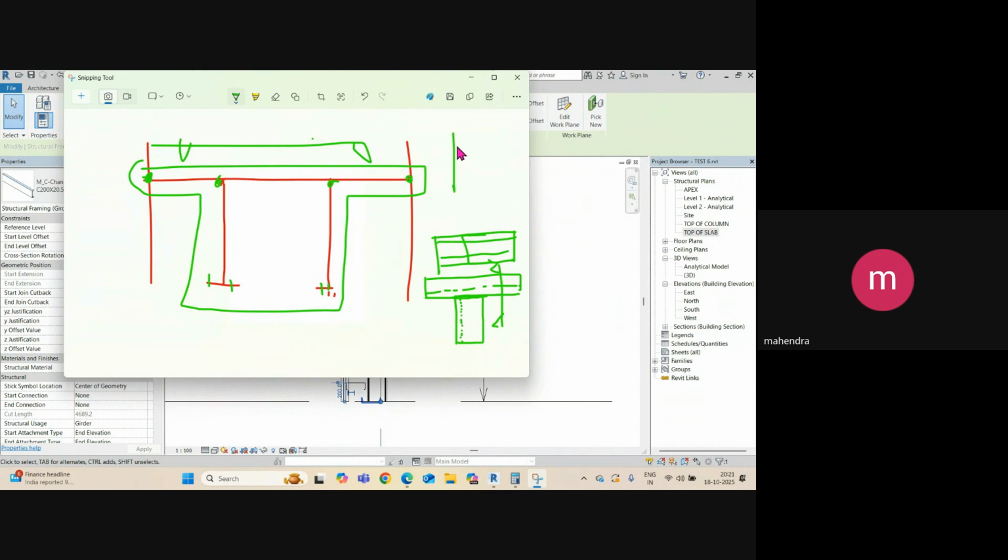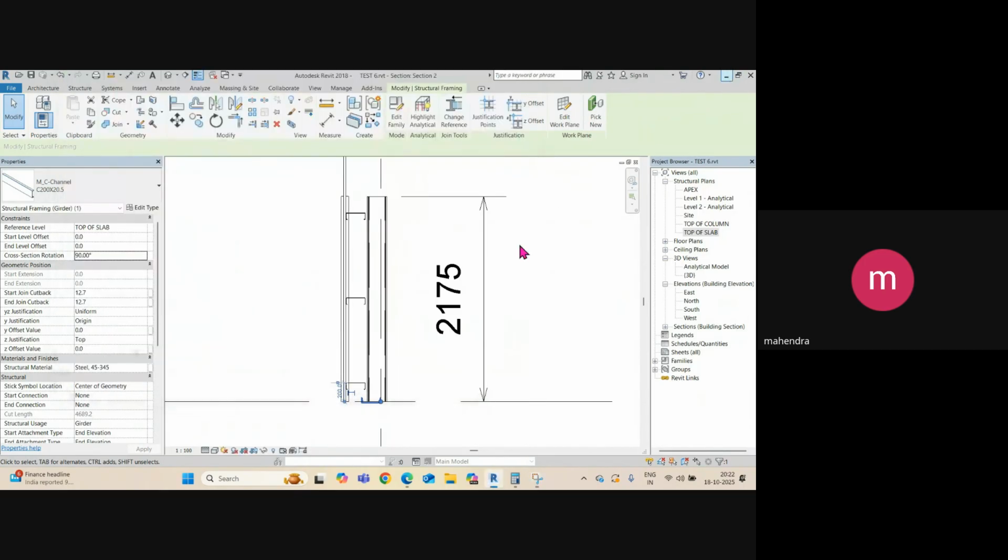So this is your column member, right? Then this is your flange, right? And this member looks like that. Suppose I give a bolted connection here, I will give a 10 difference gap, and then you can give the plate connection. This plate is welded to this beam, and you can add the 2 bolts. So this type of connection you can develop.